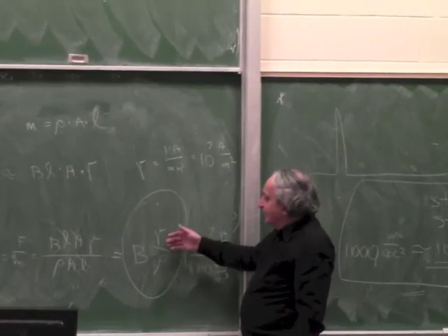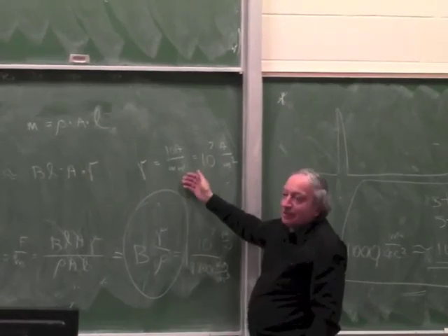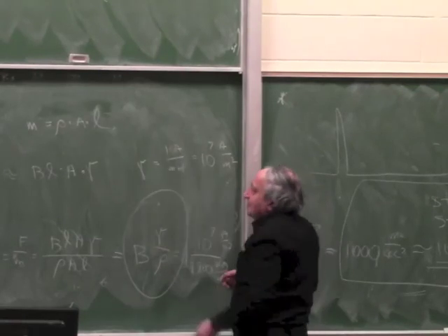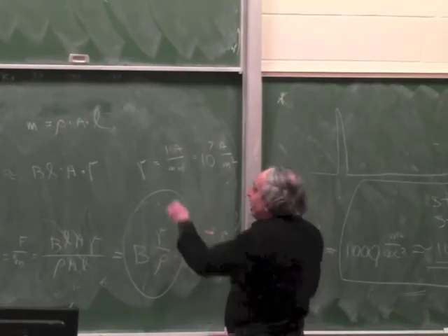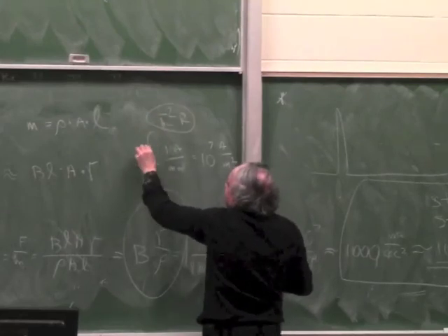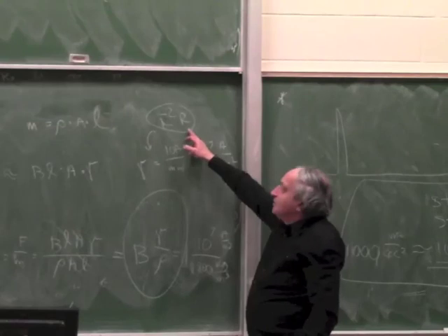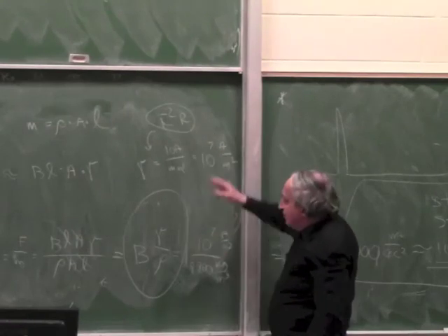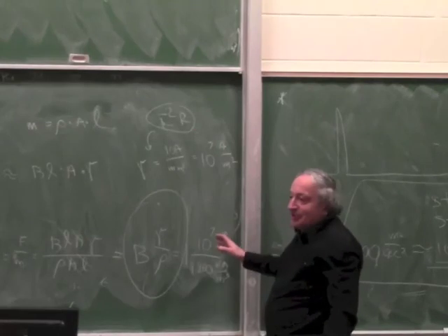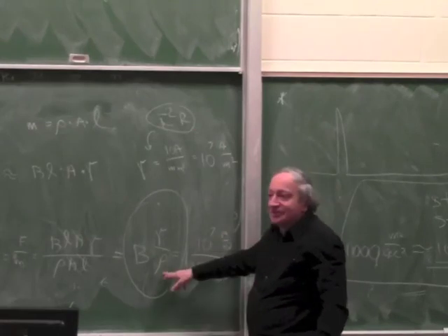Because gamma is the current density, so we're looking for the best conductor. Because the reason why you have a current density limit is because of I squared R. I squared R gives us this limit. So maybe we should find a material which has less R, or find a material which has less density. Because the performance is very simple. It's just 3 material constants.